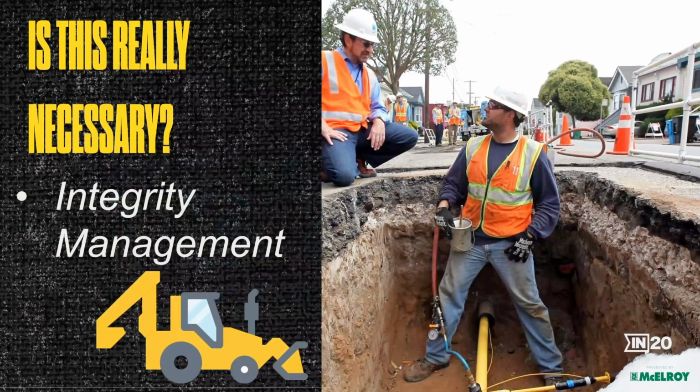Then the last point that I'd like to make about the importance of pressure testing is centered around something that you may have heard referred to as integrity management. Some pipeline operators, particularly those who fall under the regulations of PHMSA, so yes, I'm talking to the natural gas folks now, may be required to do a periodic system integrity assessment. Those assessments are intended to determine whether a potentially hazardous material carrying pipeline has adequate strength or integrity to prevent leaks or ruptures. And a pressure test is one of the ways that that assessment can be accomplished.